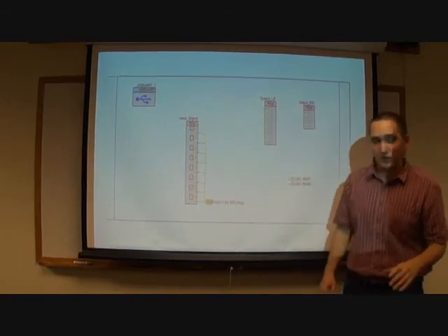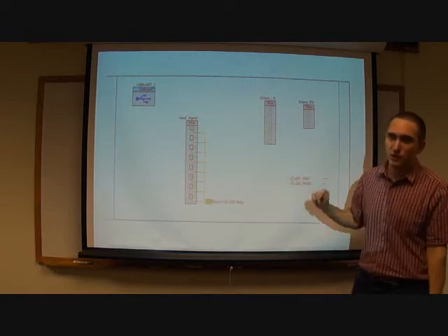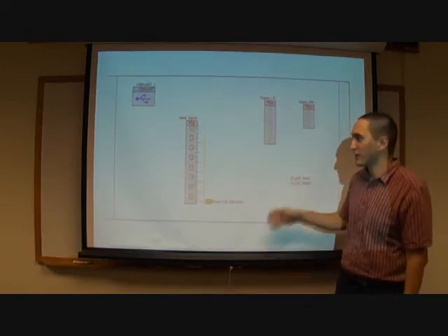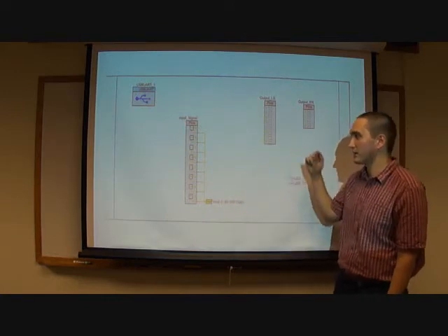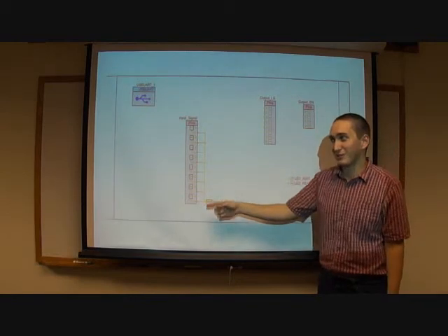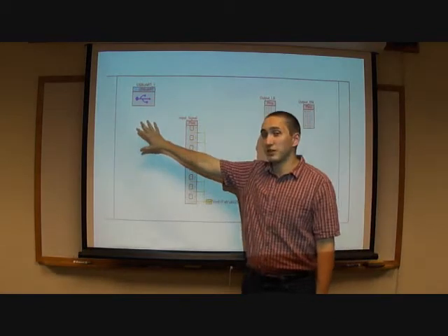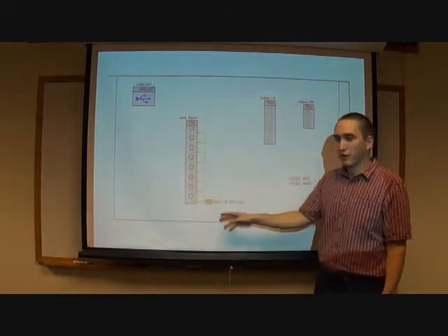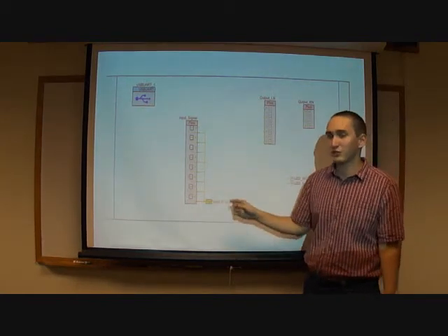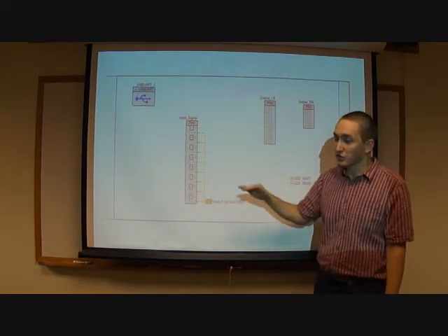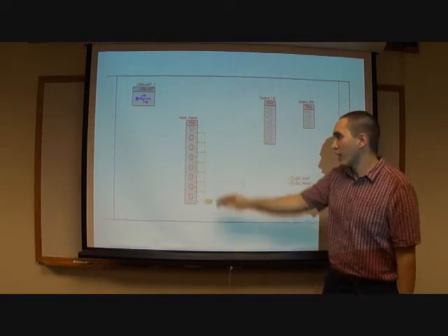Alright, now I'm going to delve into the firmware part of our top level block diagram. This is a screenshot from the PSOC5 Creator from Cypress. It lets you design and implement all the internal circuitry and how things relate to each other. Actually there's no internal circuitry, we just have output circuitry, which has our output pins, our input pins, and our USB UART. The real money part of this is the input signals, which are mapped to special input-output pins, and they let you reference inputs at a bunch of different voltages, and that's how we're going to be able to get our 1.8 volt, our 3.3 volt, and our 5 volt.